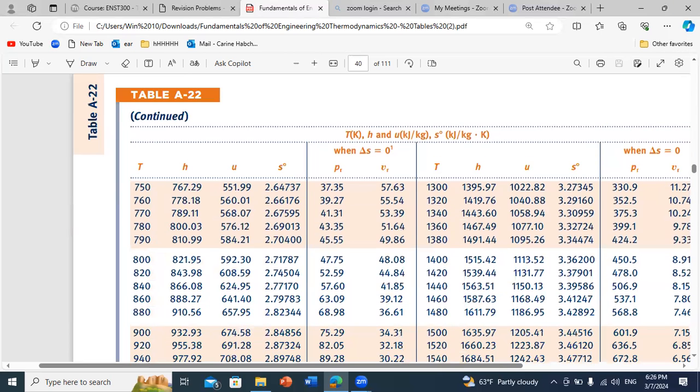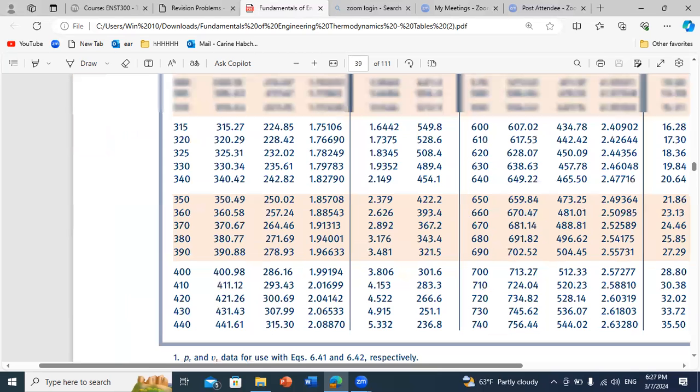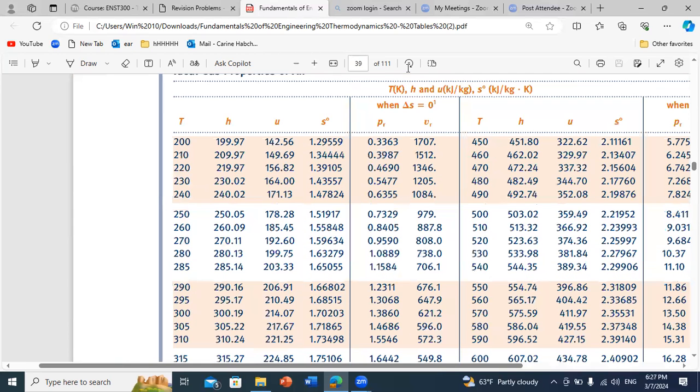So here, we know that the inlet temperature is 300 Kelvin. So we go to the table. T is in Kelvin in the table, so we just have directly 300. We can read automatically this is H at 1 prime. So this is H1 prime. Okay. So now we know the enthalpy at the inlet of our compressor.